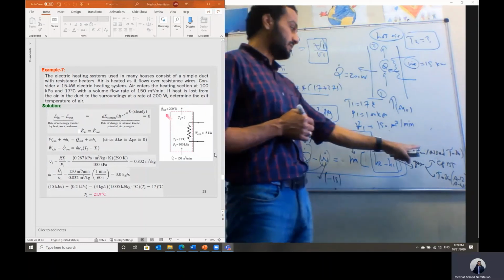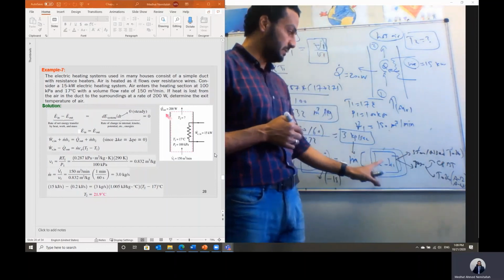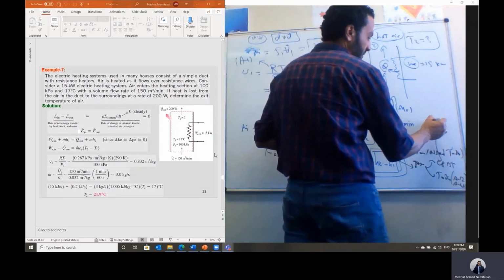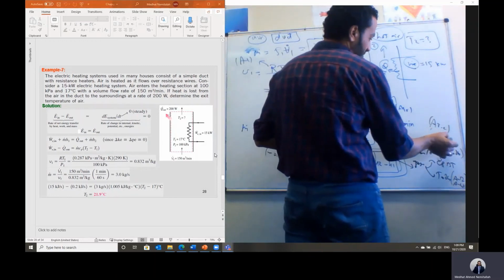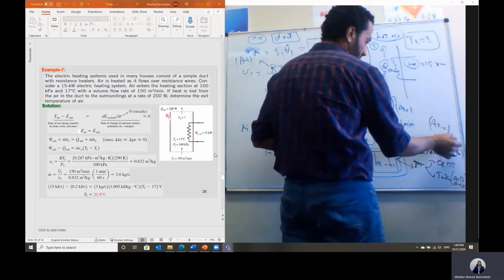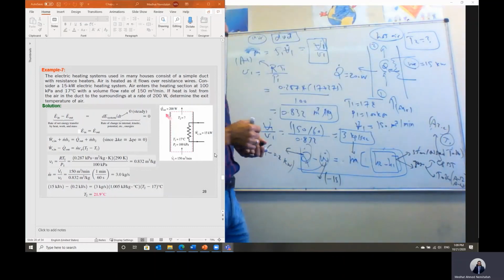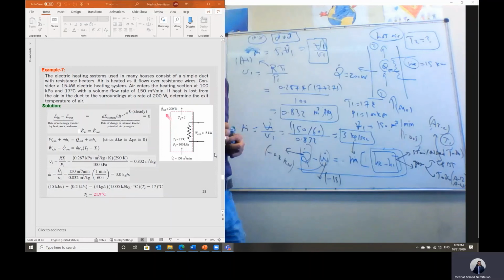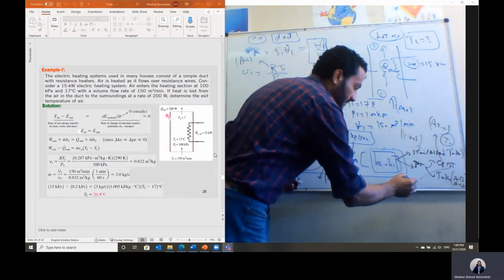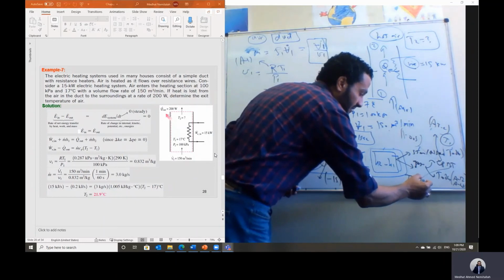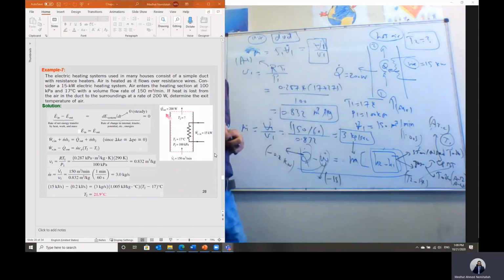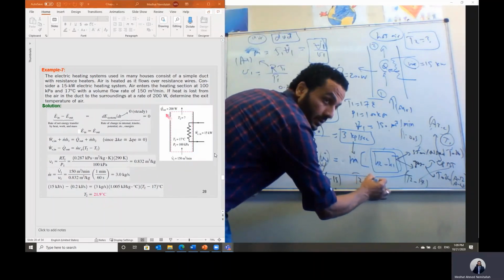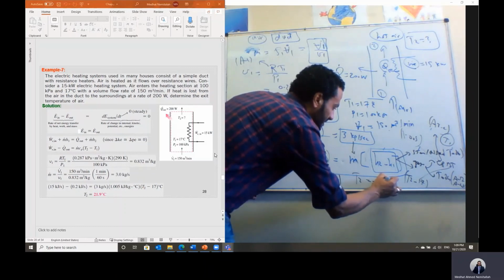The working fluid in this case is air, which is a gas. So we have either constant or variable specific heat analysis. Either we can say delta h is equal to Cp delta T, and this Cp we can just get from table A-2 for air. At the temperature here we need T2. T2 is not given, so in this case we can get it at T1. When you go to the table to get Cp, it will equal about 1.005 kilojoule per kilogram Kelvin. We have delta T, which is T2 minus T1. T1 is 17, we can just leave it in degrees C. Then we can calculate T2 in degrees Celsius. So T2 will equal 21.9 degrees.